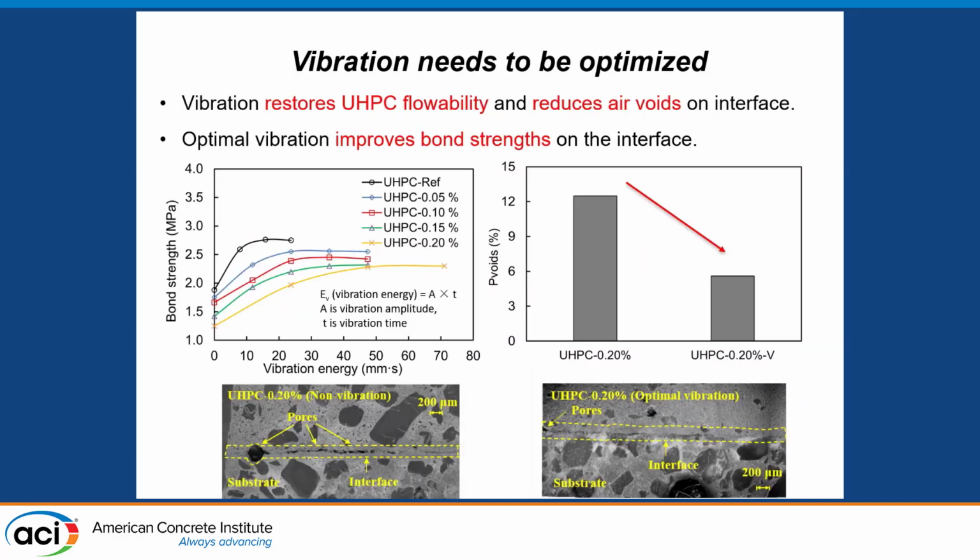So it is suggested that we should apply a little bit of vibration for enhancing the bond between the substrate and the UHPC. For each content of nanoclay, we have an optimum vibration energy that you can apply. So here shows what you can do.